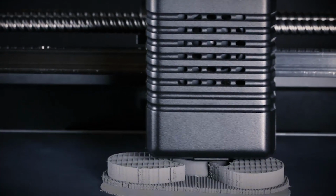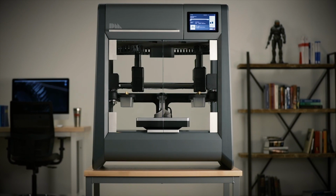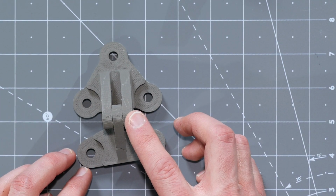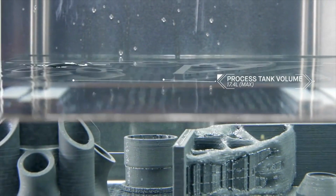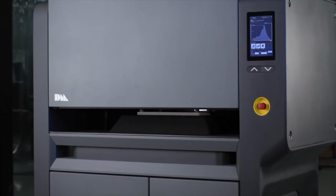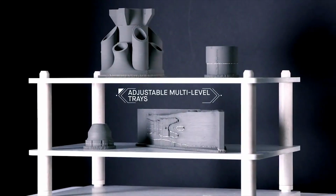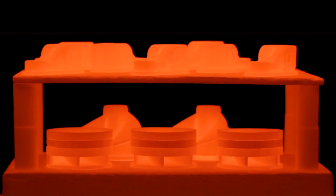We're also seeing the application of extrusion AM to metals. Now how does that work? Well, one technique by a new startup called Desktop Metal involves first extrusion of a mixture of metal powder and a thermoplastic. That creates a first part that looks like this, and then has to be taken through 2 key post-processing steps to produce the final finished metal part. First, the 3D printed part is dipped in a liquid to dissolve some of the plastic, and then it's put in an oven at high temperature. Causes the metal powder to sinter together to form the final dense finished part, and that sintering happens very close to the melting temperature, but not quite at the melting temperature.